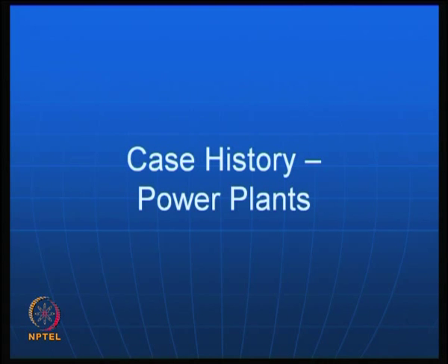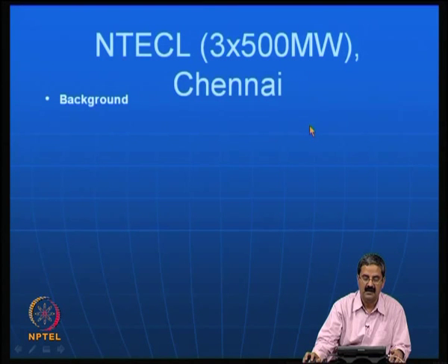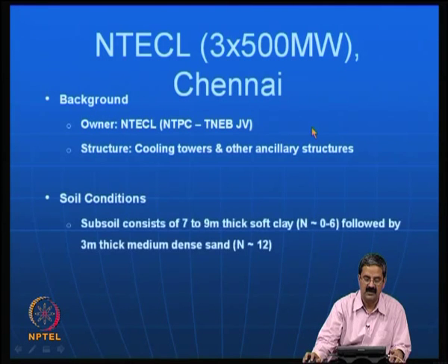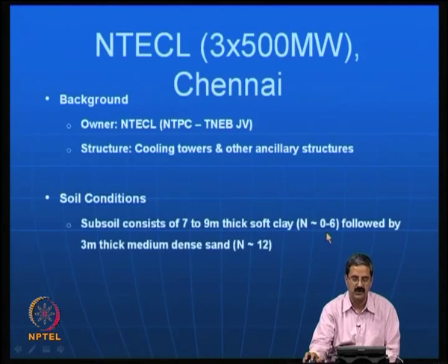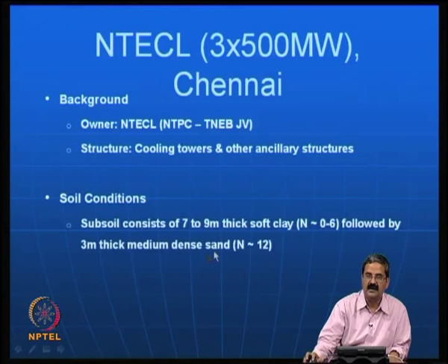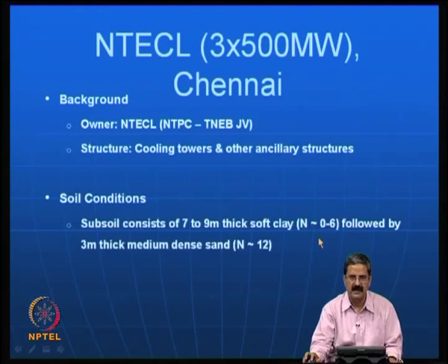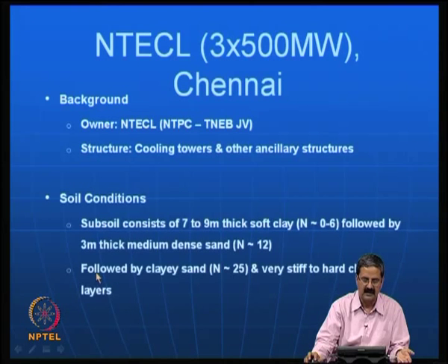Then we have some more case studies on power plants, like in Chennai, where NTPC is the owner, for cooling towers. The subsoil has 7 to 9 meters of soft soil, SPT value 0 to 6, and again it has a dense sand with SPT 12, which is actually less than 15, so it is very poor. Say for example, in a clay the SPT value is somewhat meaningless because there is a water table, and we do not know what exactly it means. Then finally you have a clay sand with an SPT of 25, and that is okay.